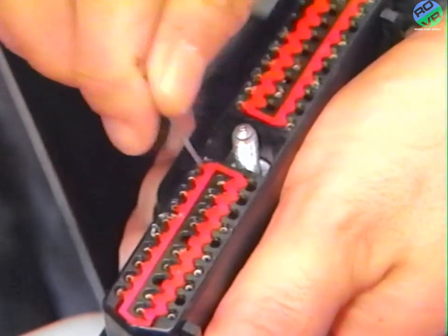As you can see, to correctly diagnose the source of a fuel injection problem, you need to know what circuits are monitored or are not monitored, and understand that a fault code can be set by a malfunction in either type of circuit. Next, we'll look at two ways of accessing those stored faults. The check engine lamp will display fault codes. The DRBII will display fault messages.